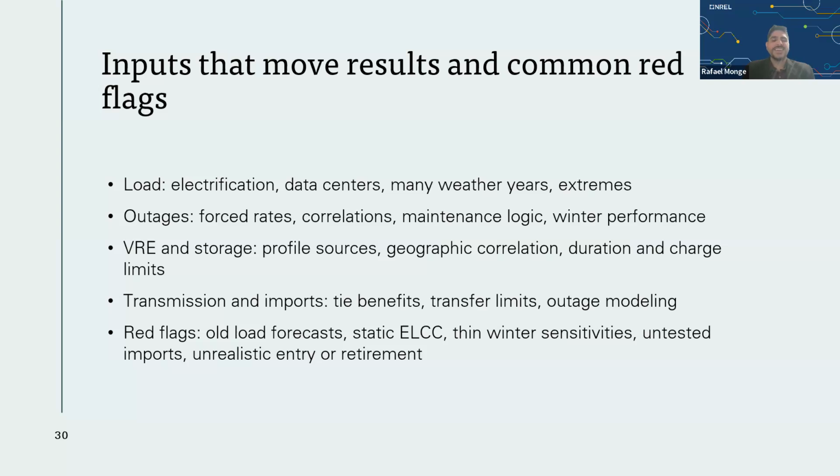Common red flags include out-of-date load forecasts, ELCC values that stay fixed while fleets grow, thin winter sensitivities without correlated outage modeling or gas constraints, also heavy reliance on imports without deliverability tests, and entry or retirement assumptions that do not match interconnection status. Any of these can materially move adequacy metrics.